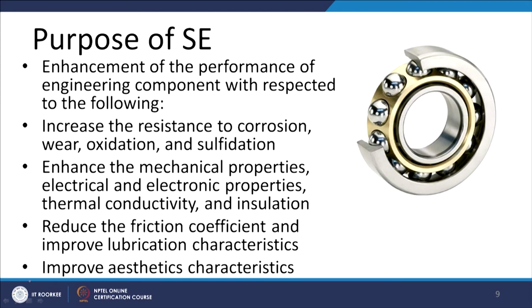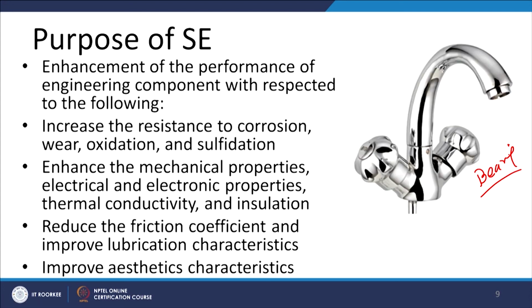For reducing the friction and improving the lubrication, like in the materials which are used for making bearing components, molybdenum sulfide and graphite kind of materials are used, so that they can provide the required lubrication. And aesthetic characteristics are improved, like chrome coating and platings are applied in bathroom fittings and watches and so on, for improved resistance to corrosion as well as improved appearance, so that they can really improve the esteem value of the